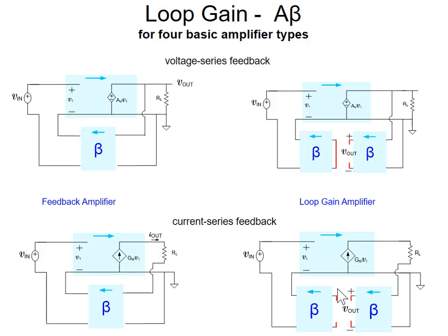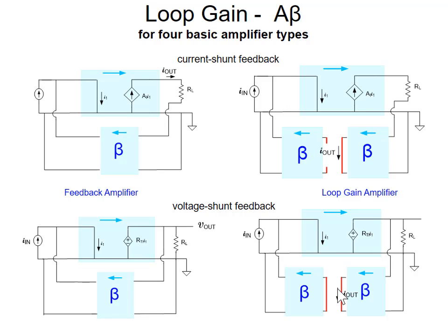There's 4 different basic feedback structures: a voltage shunt feedback scheme, and a current shunt feedback scheme. And here's the terminations on those corresponding beta networks. Make sense? Okay, so we've got a way to get a reasonably good approximation for the loop gain, although it still has some errors.